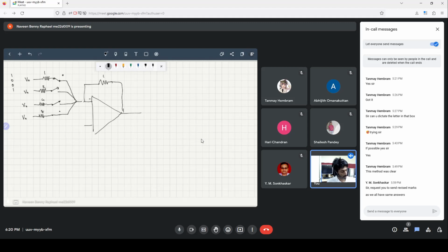The only issue is if you're having many more digits. Say you're having a 10-digit binary number, then you need resistance from 1 to 512, or 1024, which is slightly inconvenient, because if any of these resistors are slightly different, it will give a small error which will accumulate.